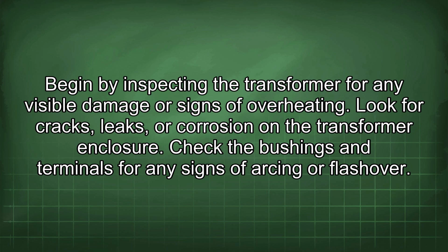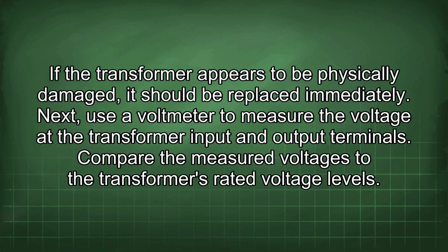Look for cracks, leaks, or corrosion on the transformer enclosure. Check the bushings and terminals for any signs of arcing or flashover. If the transformer appears to be physically damaged, it should be replaced immediately.